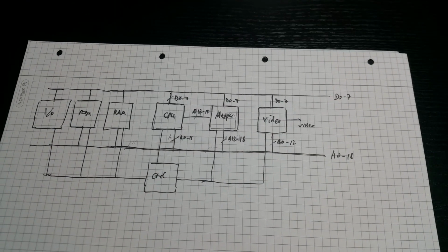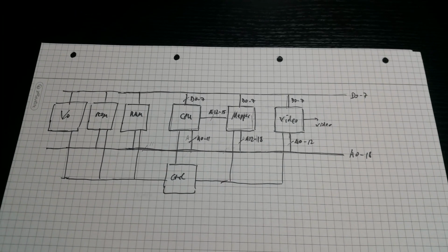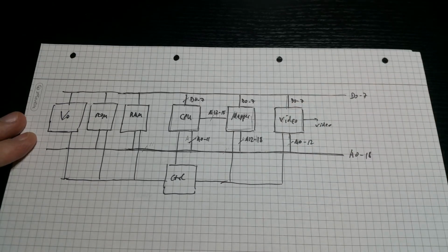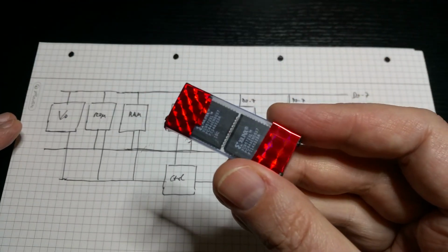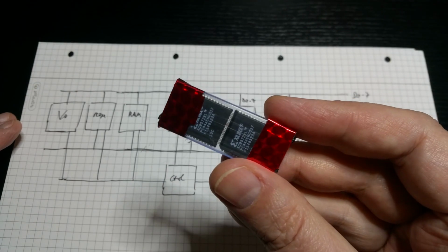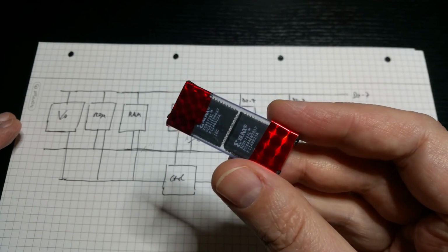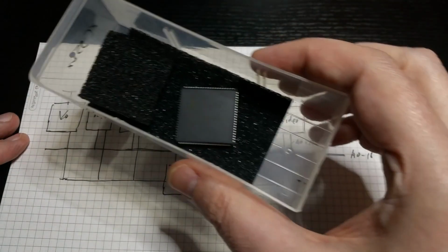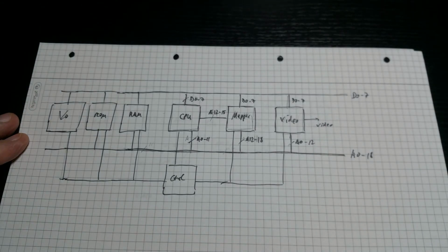So I have been looking at a number of alternatives. For example, this one here, where I had tried to build the system out of multiple programmable parts, like this controller, the mapper, and the video, all separate into these CPLD package chips that you can solder with through-hole sockets, or like even this size chips of the same type.